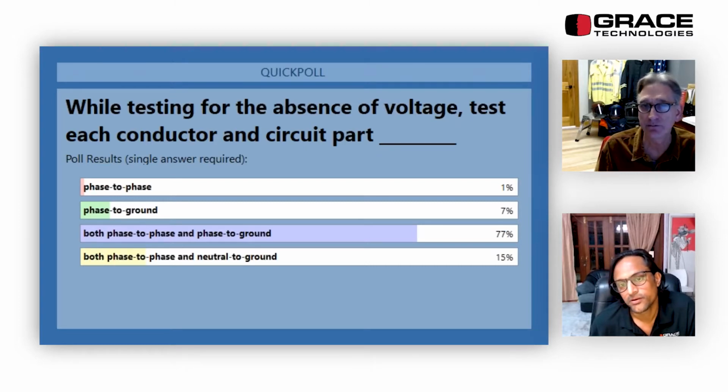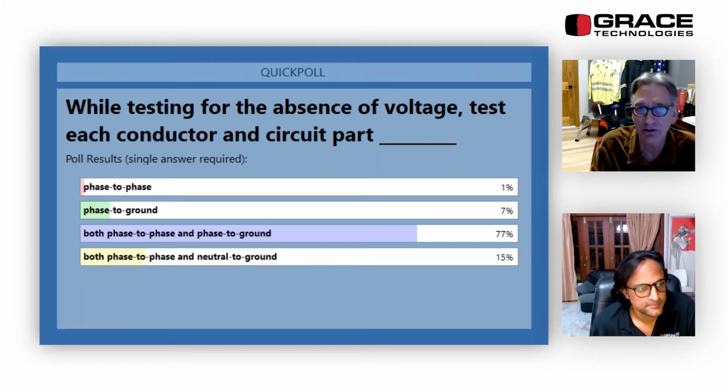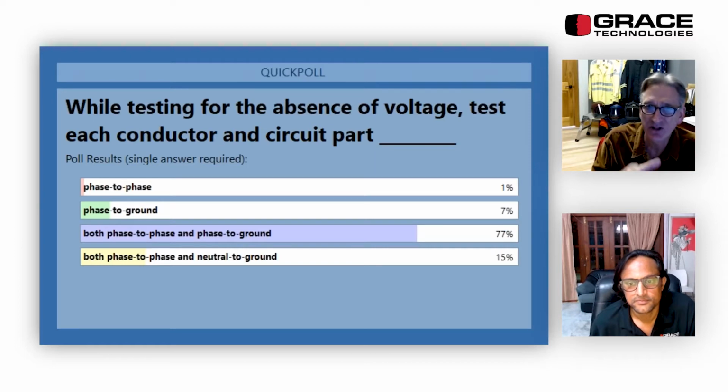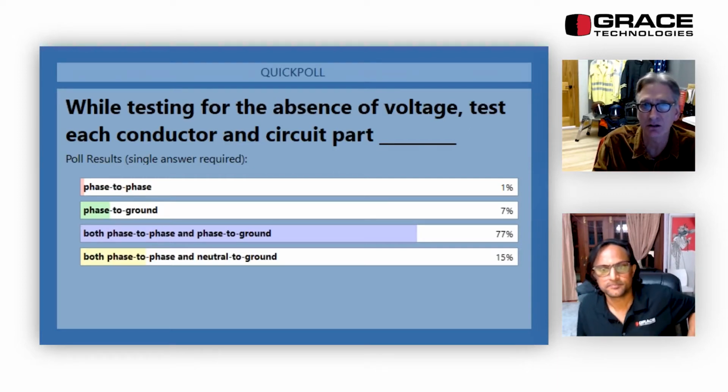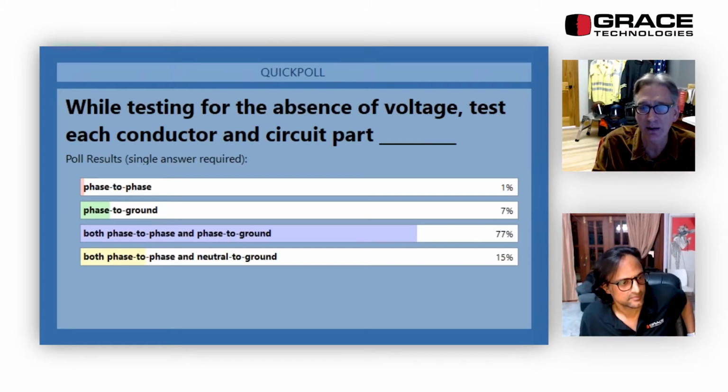And typically, if you're familiar with the National Electrical Code, we bond the neutral to ground at the service entrance, in the service equipment. Once we go away from the service equipment, the neutral and ground are not bonded together. The neutral, typically we call it isolated. In a panel board, we do not install the green main bonding jumper.